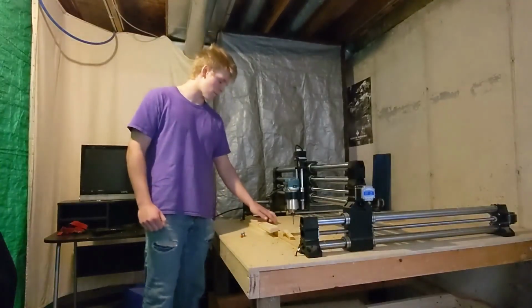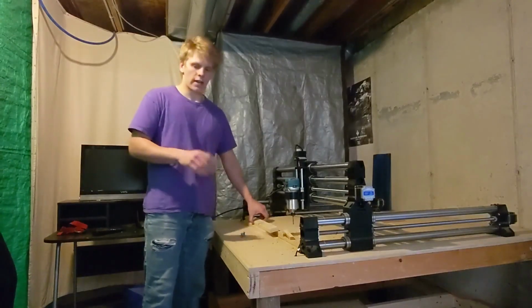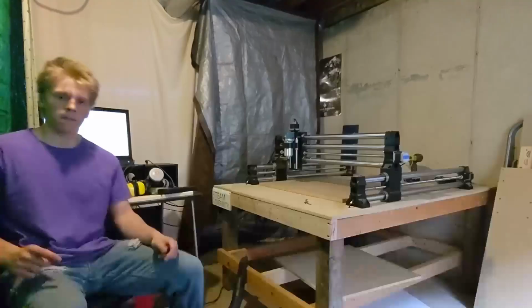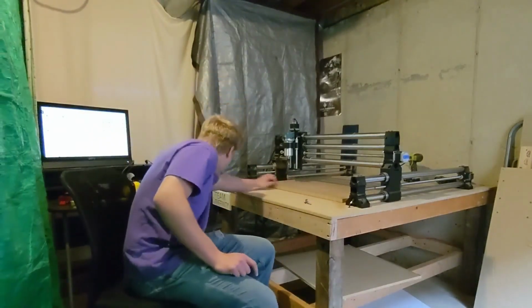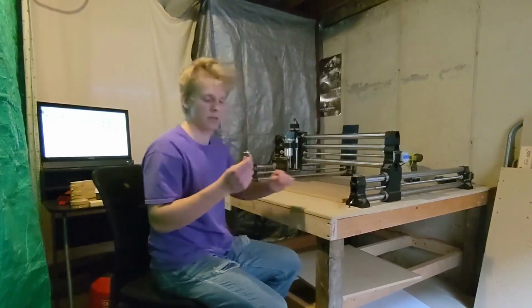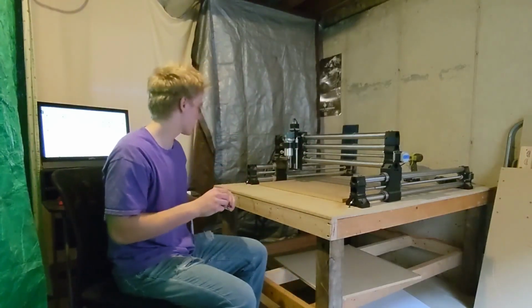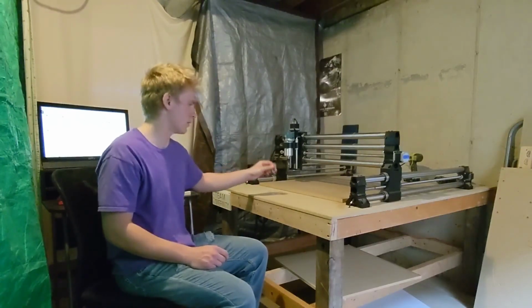Alrighty, so I got that top spoil board all cut out. So it's time to vacuum everything up, take it off, and then surface the other one. Alright, so I got the wasteboard secured, and I should have sunk these screws far enough in where this surfacing bit won't hit them. So I'm going to put this in, zero this, and then run the surfacing program.